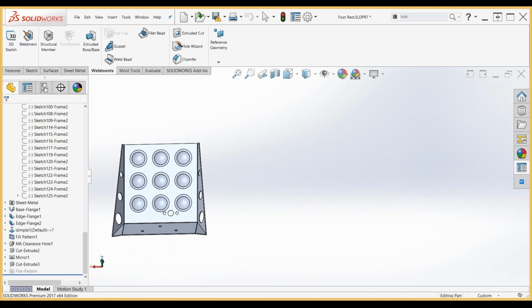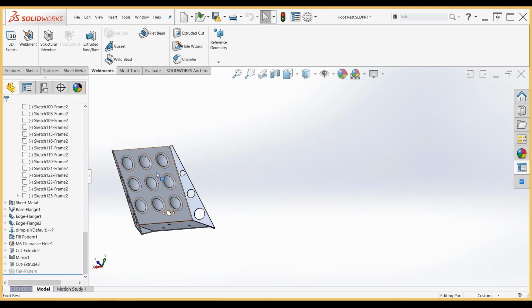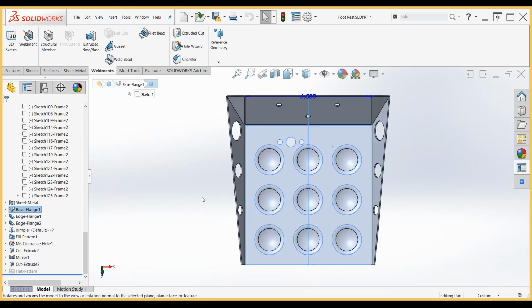says changing the standard view will change the orientation of any standard, orthogonal, named, and child views in drawings of this model. So if someone else has already made a drawing of this model and they're using front, right, left views, and I change that, that's going to change in their drawing as well. So far I'm the first one, as far as I know, to make a drawing of this part, so I'm just going to change this. Yeah, that makes sense to me. So let's make a drawing now. So we're going to grab this part and we're going to make a drawing from this part, and we're going to use that template that we spent a whole hour making.